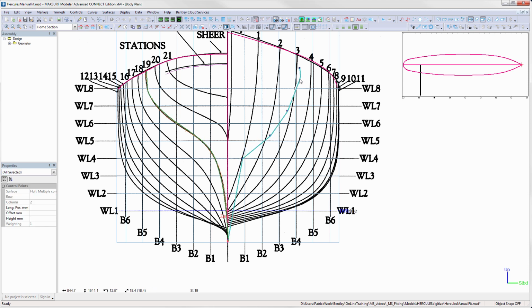It's a little bit more tricky in the stern there. We've got more of an S shape or an hourglass shape. And you can actually see there those compacted control points doing that knuckle in the transom. So again, just iterating through, starting from the beginning, working my way aft.